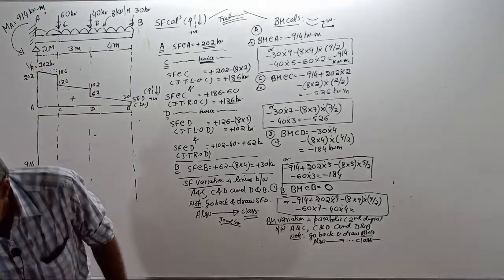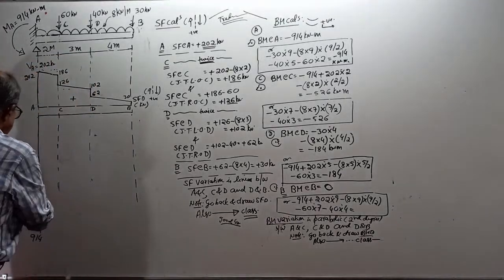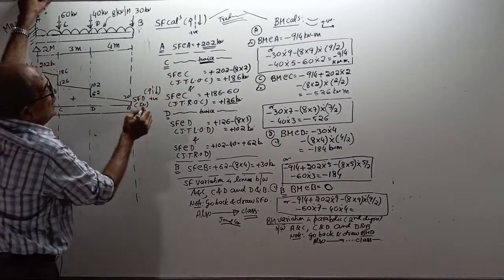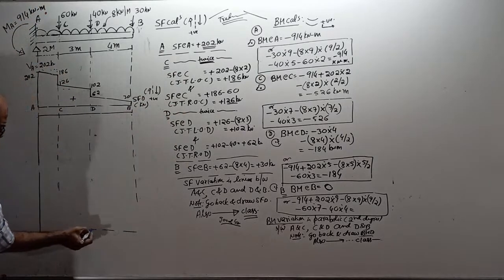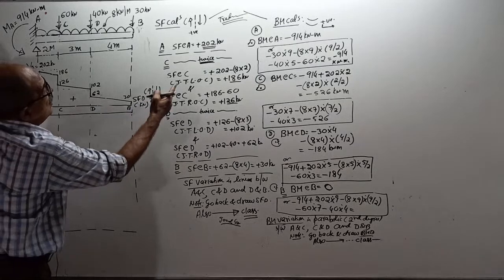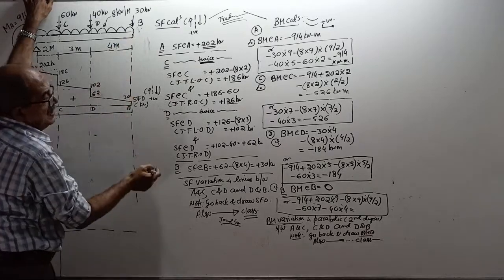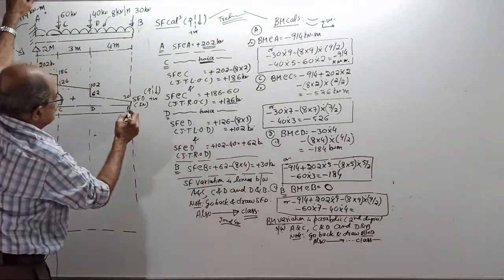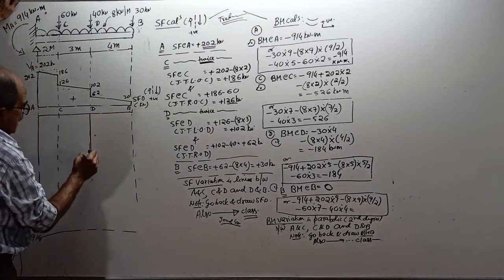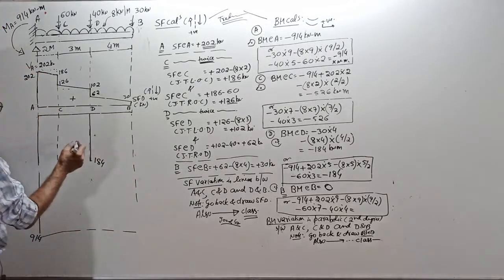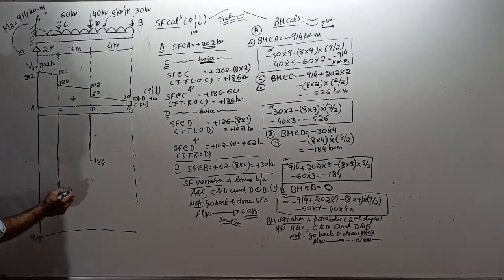Okay. Therefore, I will write 914 here. Now see, some people, I will tell you what they do. They write 0 here. Then imagine this much space is there for them. They will write first value blindly, bending moment. Actually, they will start from here, B, because usually from there, B, minus 184. Here 0. Here minus 184. They will write here. Then next they got 526. They will write 526 here. And they will write somewhere here, 91. By that time here, they will mark here 914.